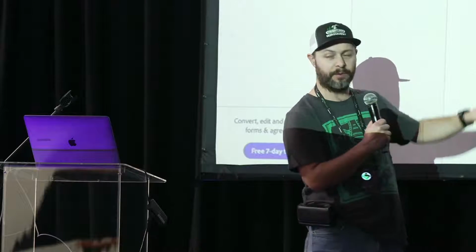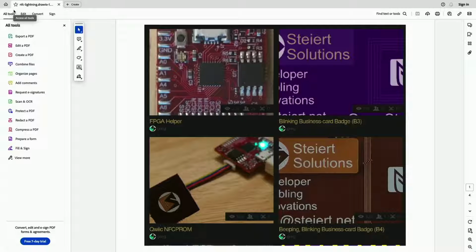The first thing I did was, NFC uses energy harvesting to power the chip and read it. So I thought that was cool, and I wanted to play with it. So I built a tiny little 1 inch by 1 inch. Actually, I think it was a Hackaday 1-inch challenge to do a 1-inch circuit board. So I actually got an NFC reader there, and it actually is energy harvesting, and there's an LED on the back that lights up, and it's got a quick connector so you can connect it to your microcontroller.